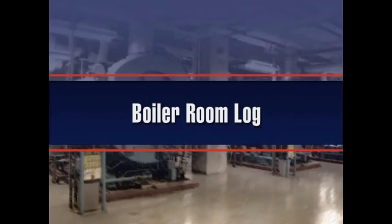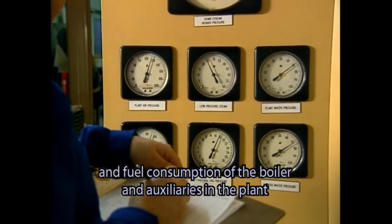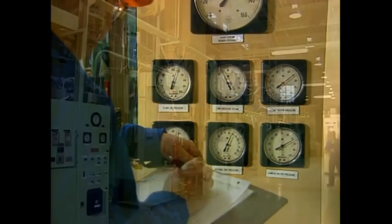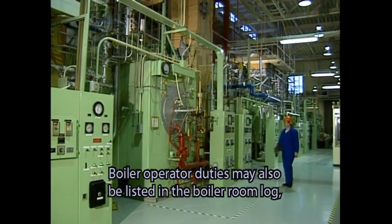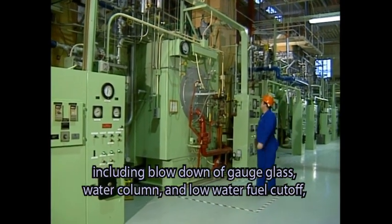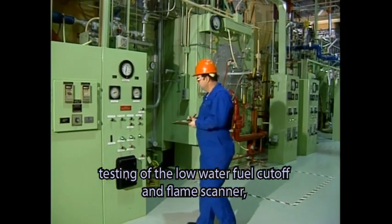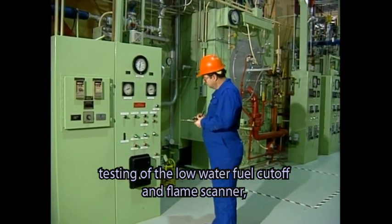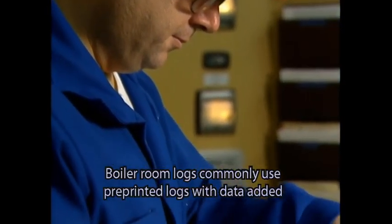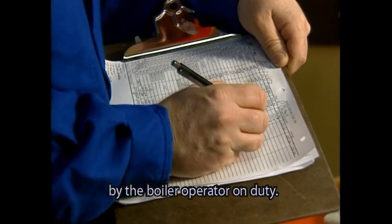Boiler room log. A boiler room log records the temperatures, pressures, and fuel consumption of the boiler and auxiliaries in the plant over a 24-hour period. Boiler operator duties may also be listed in the boiler room log, including blowdown of gauge glass, water column, and low water fuel cutoff, testing of the low water fuel cutoff and flame scanner, and maintenance work completed. Boiler room logs commonly use pre-printed forms with data added by the boiler operator on duty.